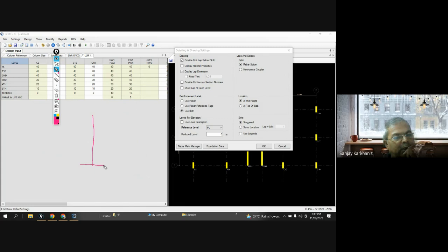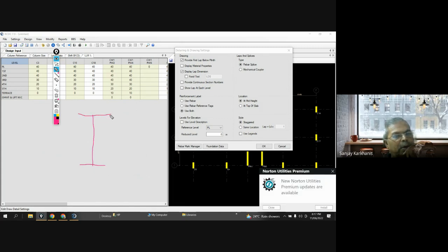See, this is my column. A slab over here, a slab over here, and if this column is subjected to lateral loads and has to resist the lateral loads also, then if I see my bending moment diagram, I will get a bending moment diagram either something like this, or you may get something like this. So let us say this is mid height. At mid height, the bending moment is 0.